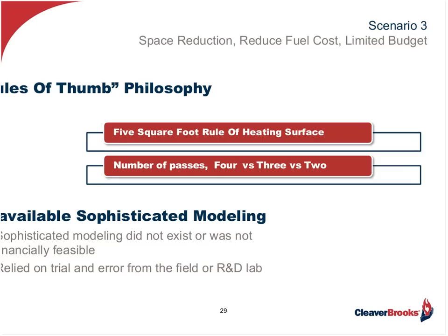At this point, what I'd like to do is apprise you and acquaint you of where the fire tube industry is going today. Years ago, when I came into this business, 5 square feet of heating surface per boiler horsepower was dogmatic, if you will. It was just a given. Today, with some of the modeling tools that we have available to us, and the expert engineering that we can take advantage of in this industry, we're getting away from that 5 square foot per boiler horsepower norm.